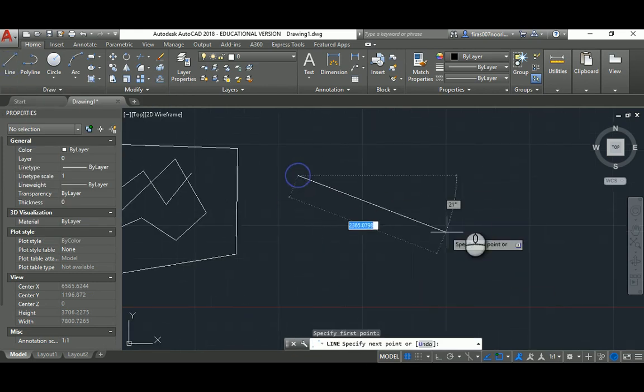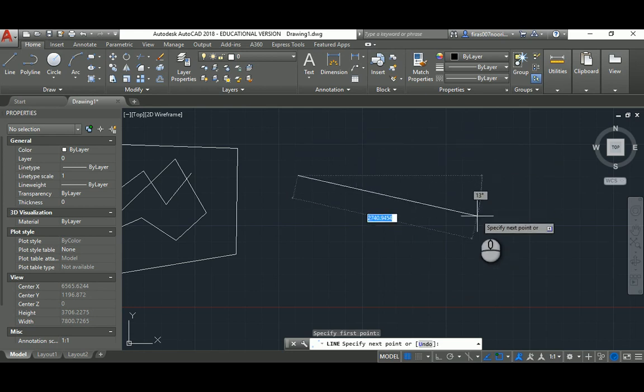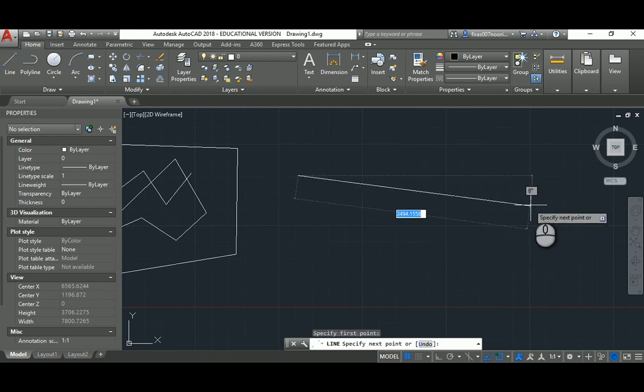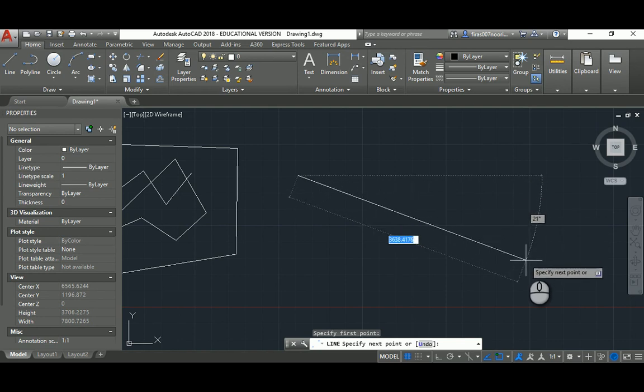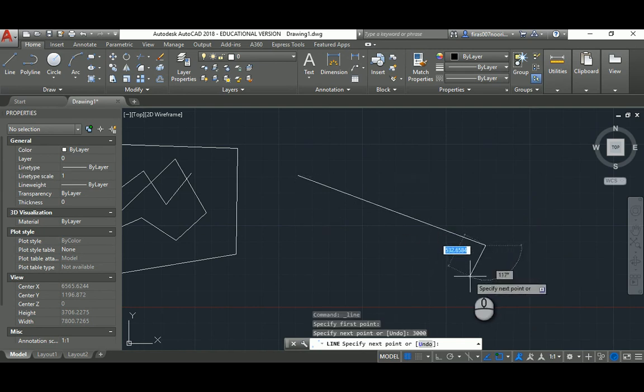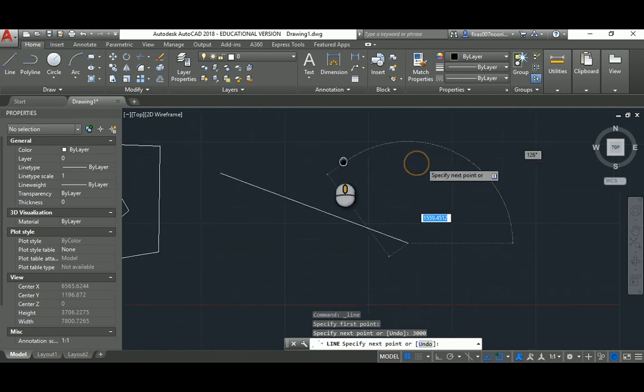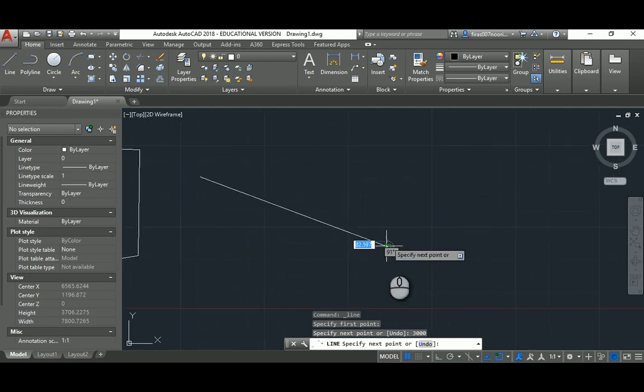So again, it's going to work loosely, it tells you roughly the angle. You can say 17, 12, and the length of it. And if you like this angle, like 21, you can go, let's say 3,000 something, then it draws the line straight forward with 3,000 units and with a 21 angle from this side.